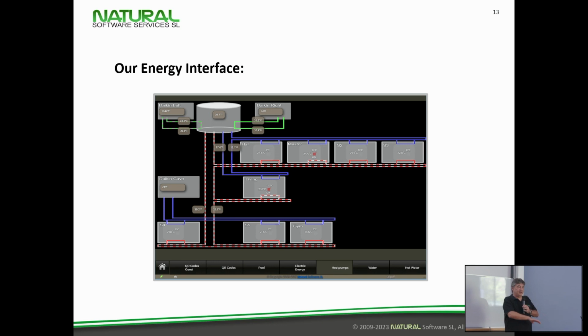This was messing up our load schedule for the batteries, because the solar energy was being used for the pool pump, but not for loading the batteries. So we changed the schedule of the pool pump to 2 hours later, and all of a sudden we got, I think, a 5 or 6% increase in the value where we were independent of the electrical grid. So changing little parameters has a pretty big effect on what is really happening.